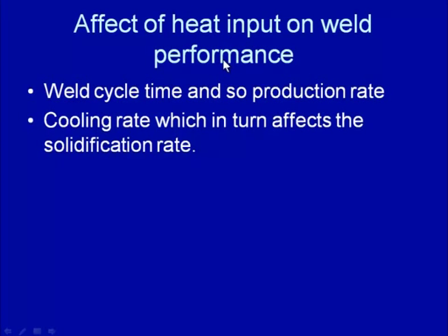And heat generation also affects the rate at which the weld metal will be cooling. Since if the heat generation and the heat application is more in case of the fusion welding processes, then it will be decreasing the cooling rate, and decreasing the cooling rate will be increasing the time required to solidify.